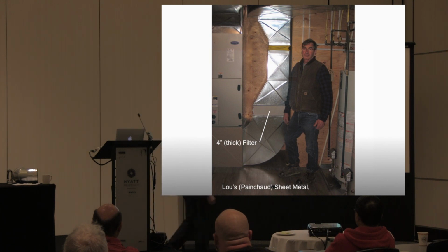A 3-ton heat pump, a massively large radius throat, wheel, turning vanes, filter where it should be. Filters are rated for the air to hit them square on. They're not rated to go in adverse conditions.